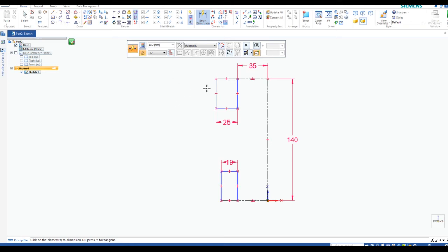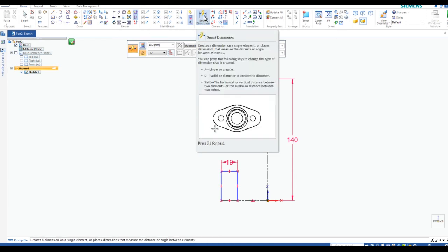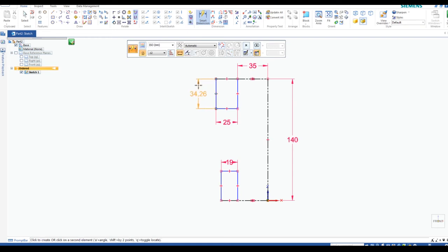We now, however, need the overall, or the actual radial distance. So if we take a look at the top, it is 48. So at 48, we will put a radial dimension. 48 divided by 2 is 24. Okay, and we'll do the same thing with the smaller one. We'll click. That is 32, so 32 divided by 2 is 16. Okay, so now we have the overall sizes.